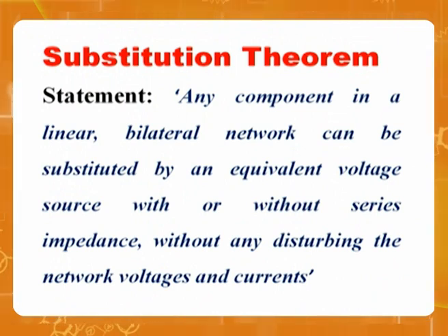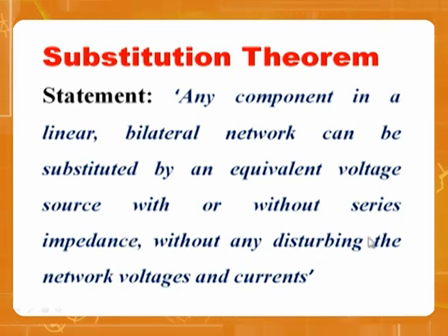Now let me take you to the third theorem, the substitution theorem. When you say substitution theorem, let me give the statement. Any component in a linear bilateral network can be substituted by an equivalent voltage source with or without series impedance, without disturbing the network voltages and currents.